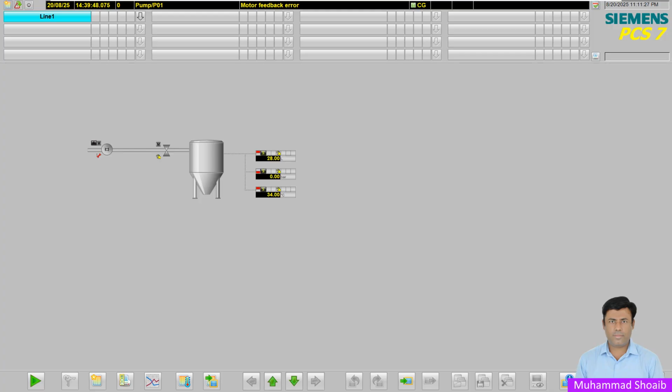Start and stop control: enable or disable our motor, or open or close the valve. Parameter changes: allow or restrict access to tuning parameters like PID parameters. Alarm acknowledgement: whether the operator is allowed to acknowledge alarms. So typically, operator control permissions are there in each of the blocks.